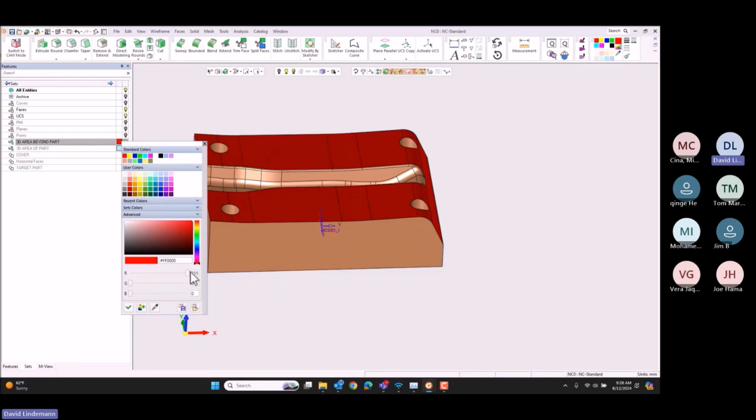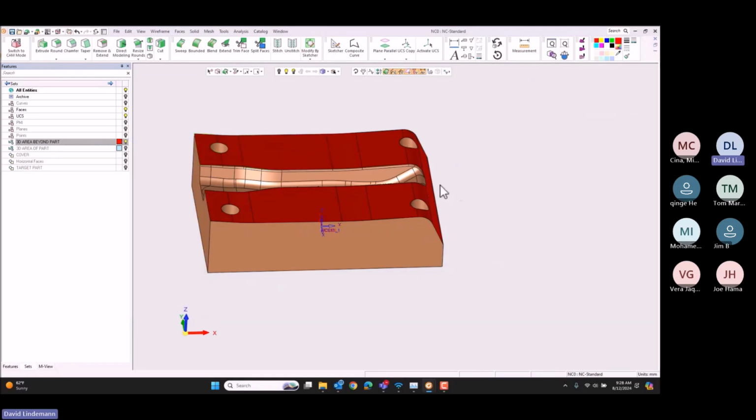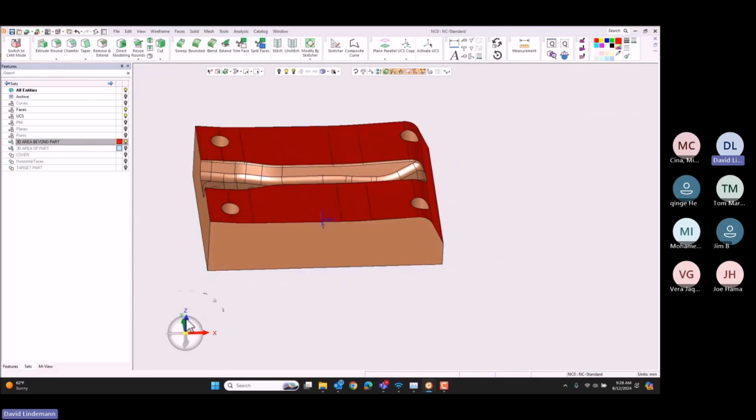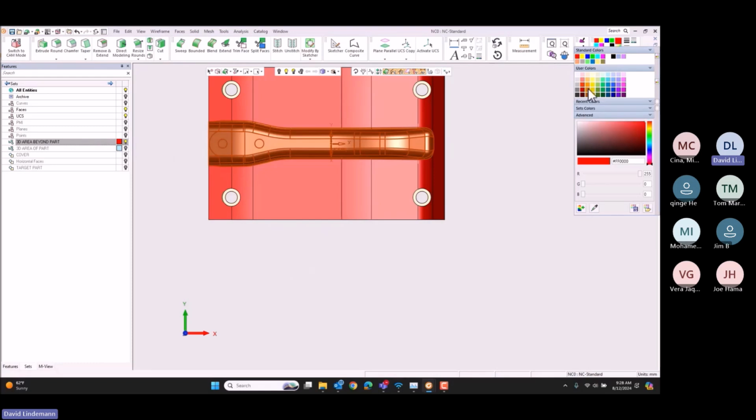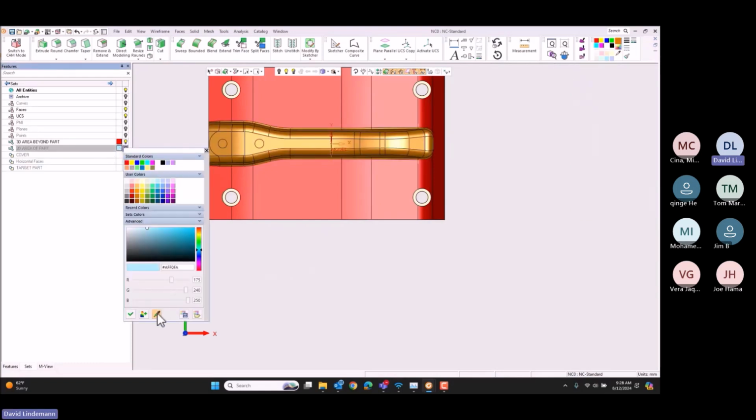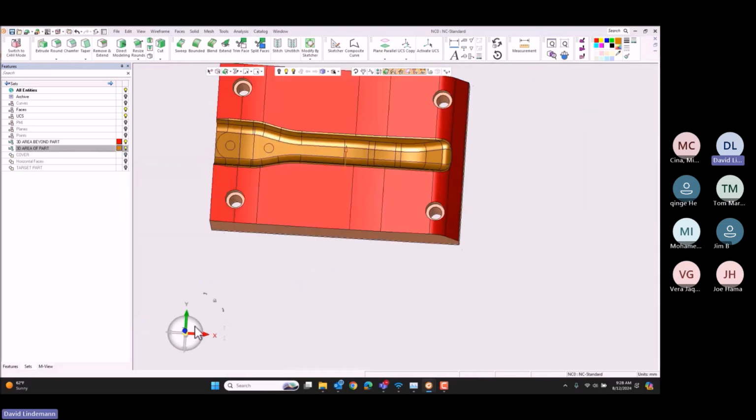So pick all that by color. That goes on to what we're calling the beyond part area, which is basically the run out binder area. Then we'll take what's in the middle, that's the actual part area. Now, since those sets are named the same, we can go ahead and apply that template by looking for set name. Okay.